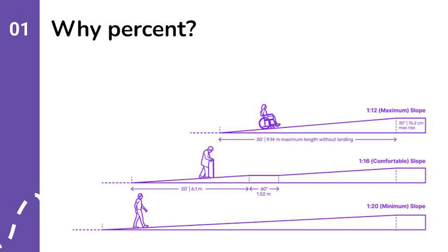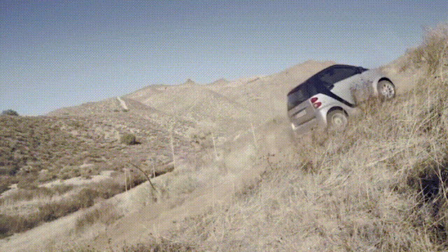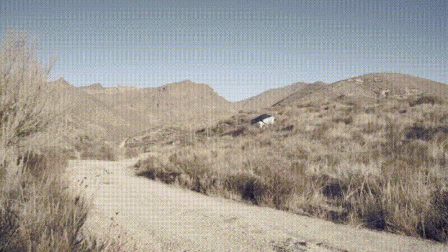Engineers and planners particularly like to write slope in percentage, not degrees. A 25% slope is around a 14-degree angle if you prefer that. We do this mainly because it's so much easier to do the math, and we sometimes have to do a lot of math. To visualize this, a 10% slope is a moderate incline. A wheelchair ramp is around 6%. A 25% slope is so steep that most vehicles, even off-road vehicles, cannot climb it.